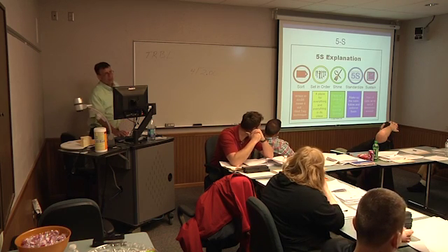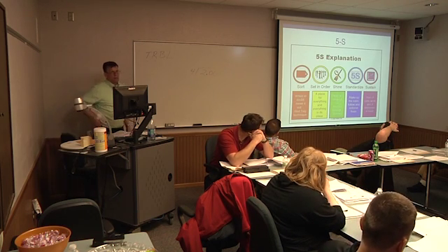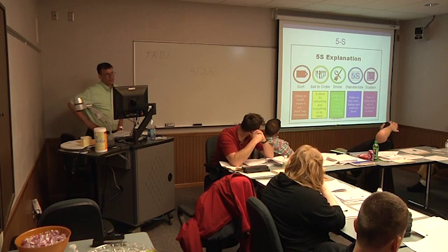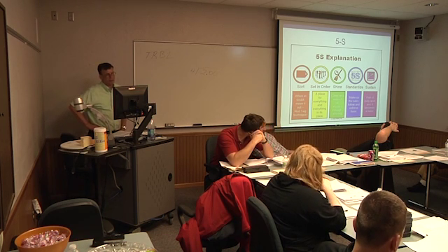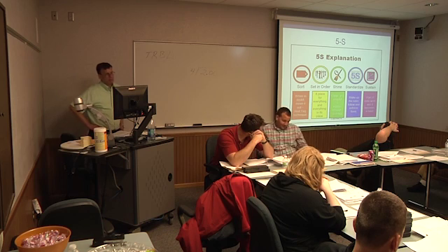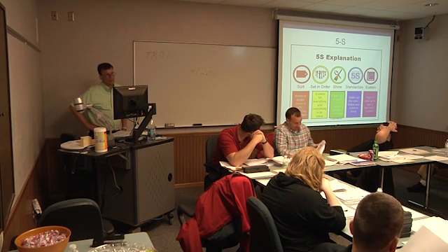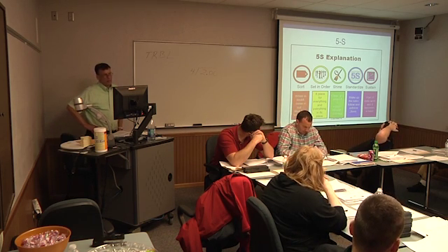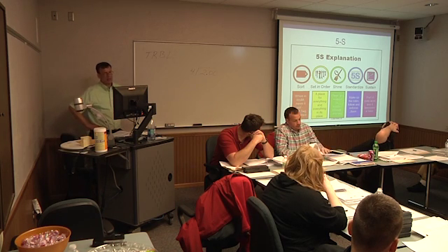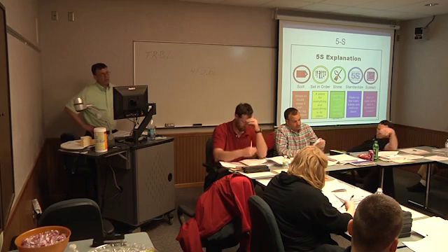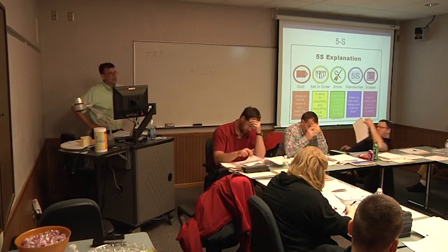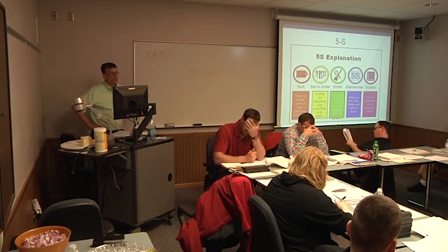5S, this is a practice that's used in some quality organizations. As its name suggests, you've got 5 things that begin with the letter S. Good illustration here. First you sort, and then you put things in order. You shine or clean. You standardize it. In other words, you maintain that practice indefinitely. You don't change your methods.